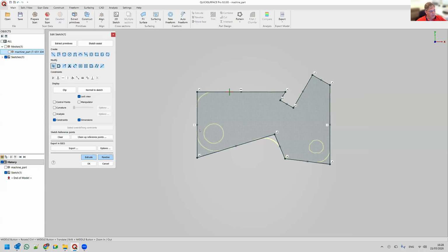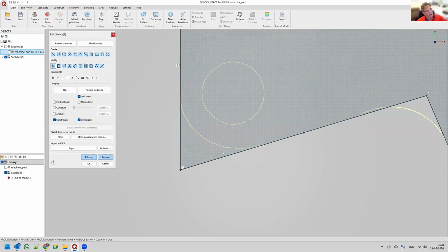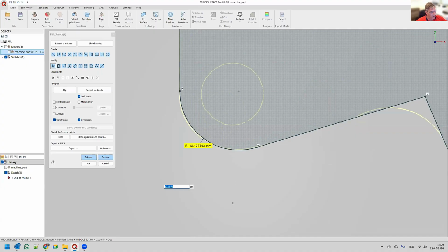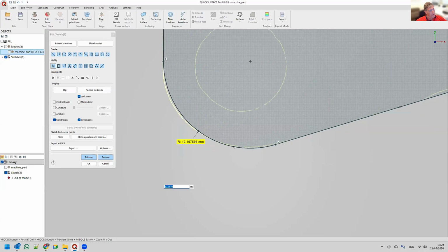But we don't have these fillets here. If you remember, I was telling you about the smart detection, what is this radius? If you press Control and just brush over a corner, it automatically will determine the scan data underneath and suggest a radius that can be used in this case. Again, this is a fillet, but the part is completely damaged or changed, so it's really in your hands what to do.